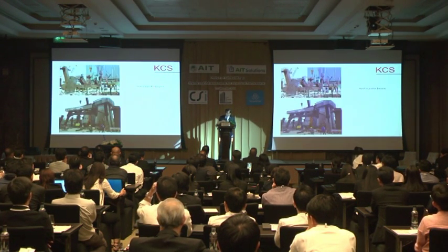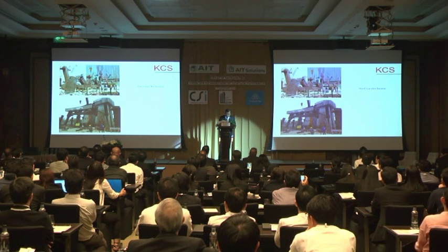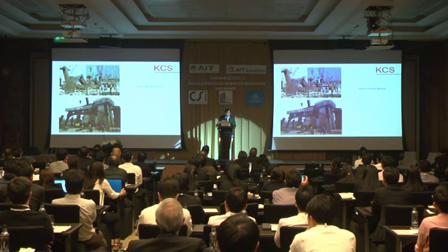Large-scale steel transfer beams were used to eliminate the heavy shoring system, and mass pouring of concrete at a higher level of the building.